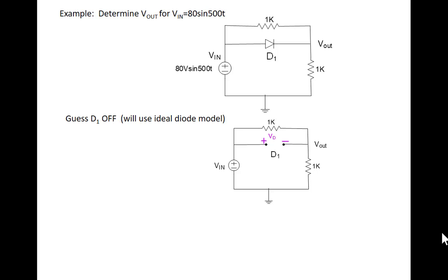This is a nonlinear circuit. Can I use linear circuit principles to solve this circuit? For the simplification, yeah, once we simplified it, it's now linear, right? So I can use the voltage divider equation, and the output voltage is Vn over 2. So I'm just going to do this off to the side. Here's Vn, and V out is equal to Vn over 2. So it looks like this dashed line here.